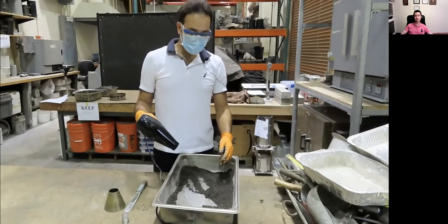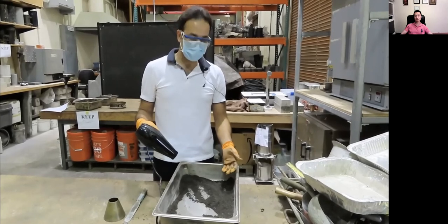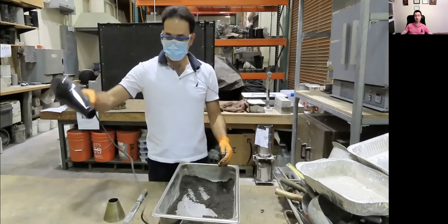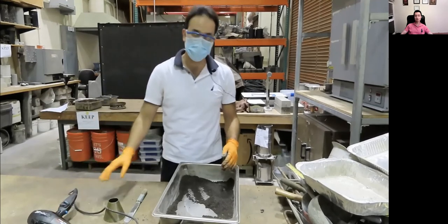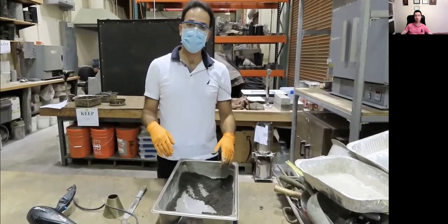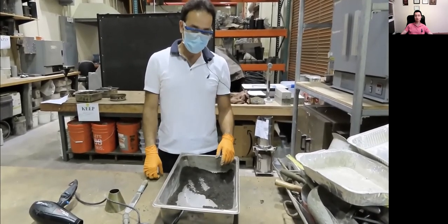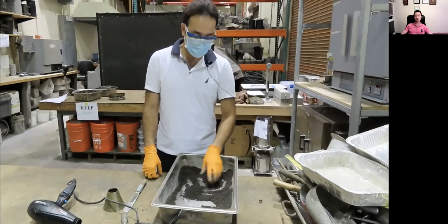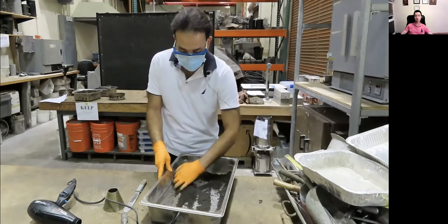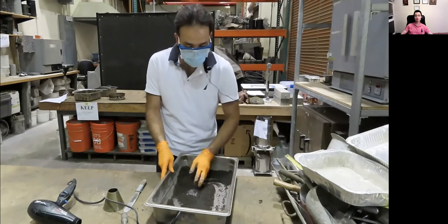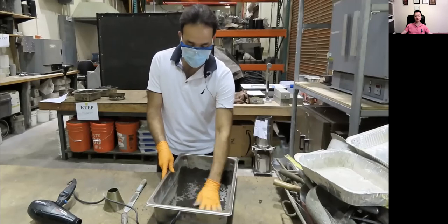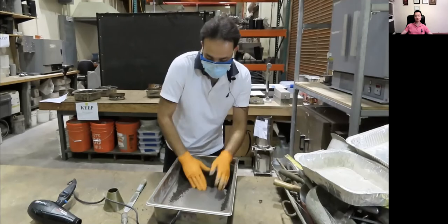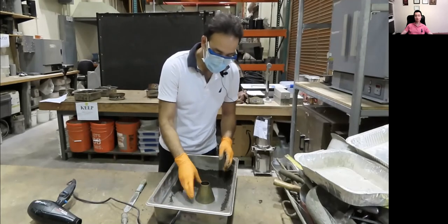Okay, I'm drying my fine aggregate for about 20 minutes, and want to test if it is enough, I mean, if it is in SSD condition. As you saw while I dry my aggregates, I try to stir all around the container to make sure that the moisture of the fine aggregate is uniformly dry. But for the test, if it is in SSD condition or not, I just need to use this cone.